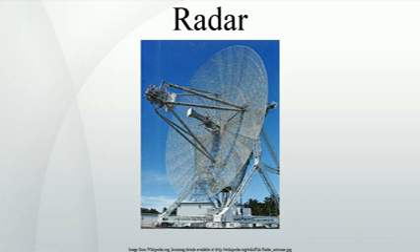A further advantage is that the radar can operate effectively at relatively low frequencies. This was important in the early development of this type, when high-frequency signal generation was difficult or expensive. Terrestrial radar uses low-power FM signals that cover a larger frequency range. The multiple reflections are analyzed mathematically for pattern changes, with multiple passes creating a computerized synthetic image. Doppler effects are used, which allows slow-moving objects to be detected as well as largely eliminating noise from the surfaces of bodies of water.